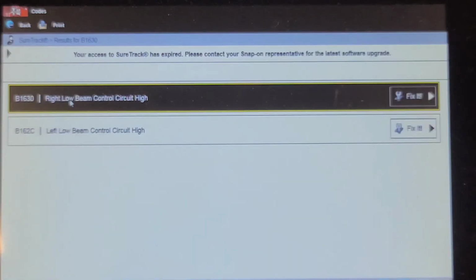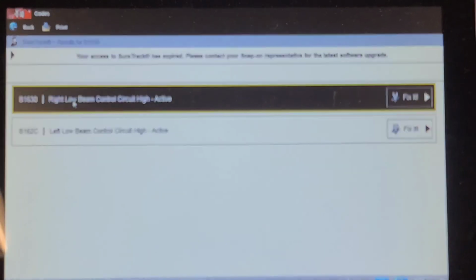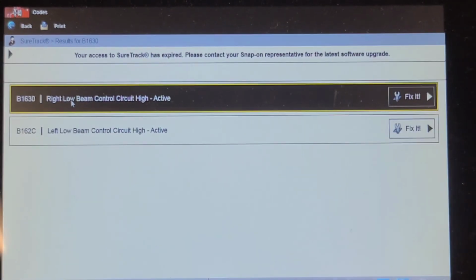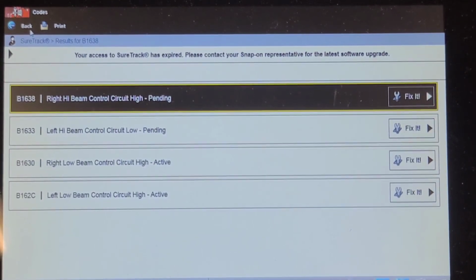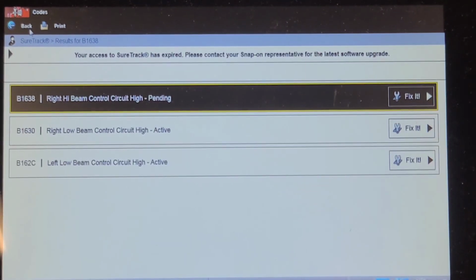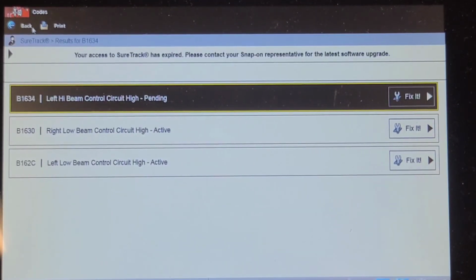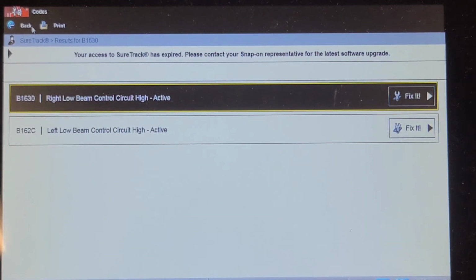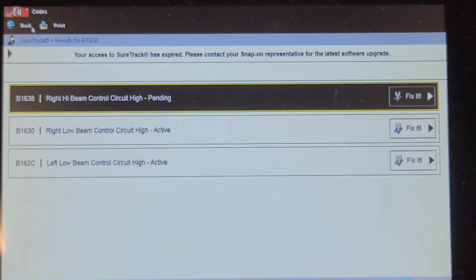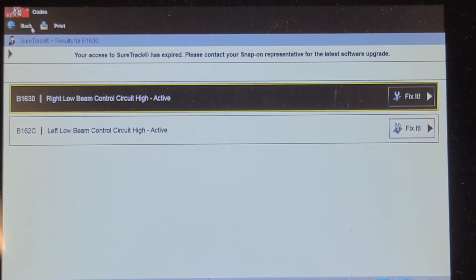As soon as I switch it to high beam, it generates a fault code. Now, as long as there's no warning indicators on the dash, we're going to let it go like that. Yeah, those LED lights are generating fault codes, but they're working fine. Yeah, smoke and mirrors. I'm going to plug in the conventional light bulb on one side.